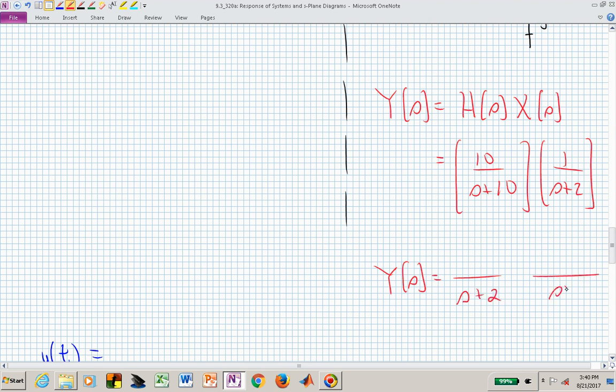We now have two real poles, another reason why we wanted to start learning how to inverse Laplace transform, and we can do that by partial fraction expansion. We now have two factors. It's strictly proper. If we were to find these partial fraction expansion coefficients, we would find that each has the same absolute value, 10 over 8, or 1 1/4.